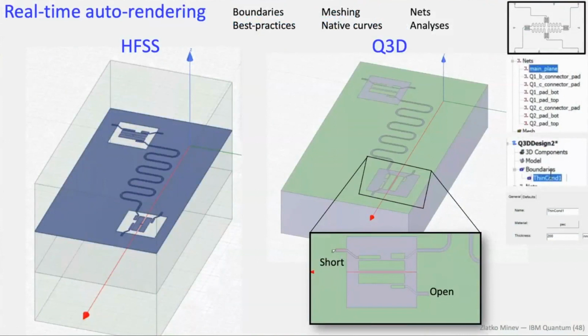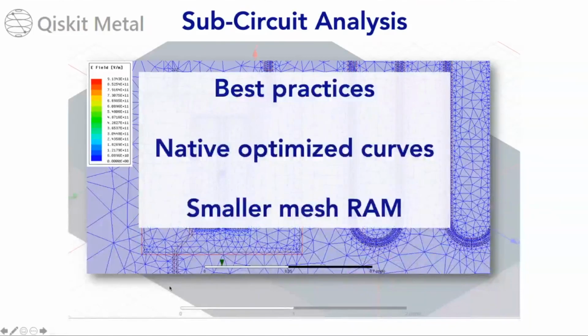This is 2D, but once the number of qubits becomes larger, it will become a 3D kind of chip. So at what number of qubits will that turn to 3D? Any inputs? Yeah, well, the actual simulation is 3D, even though the layout is planar. The simulation is fully 3D. It doesn't take approximations. This particular one here, HFSS, solves Maxwell's equations with no approximation. How much you can simulate depends on how big of a computer you can buy or have.